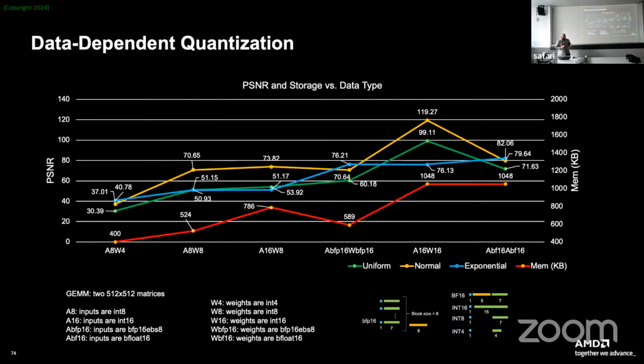So you add a little bit of real estate into your hardware, and also move a tiny bit more data per value, but you get that bump in your PSNR. So BFP16 is known as a casting data type, meaning if you quantize your values with BFP16, you pretty much don't need post-training quantization or quantization error training. You don't need any of those. You just cast it. But if you go to lower precision, you need some algorithm to get rid of the quantization noise.